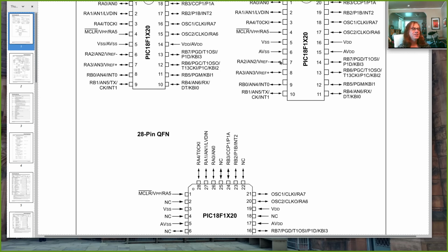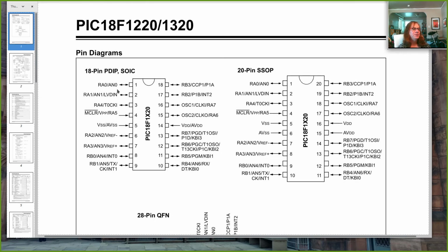And we have to tell the CPU, hey, I would like to use pin 9 to read RB1. And I'd like to use pin 8 to read AN4. So you have to condition your pins. Before you do anything, you have to set up what it is that you want to use the different pins for. So you've got to specify that.